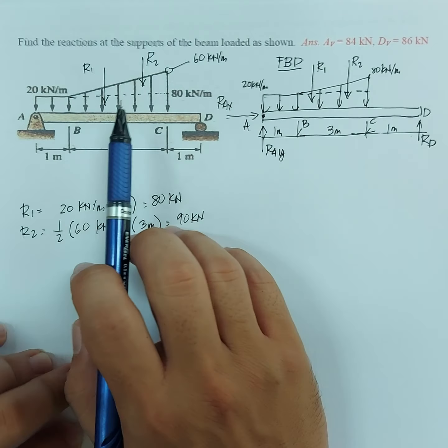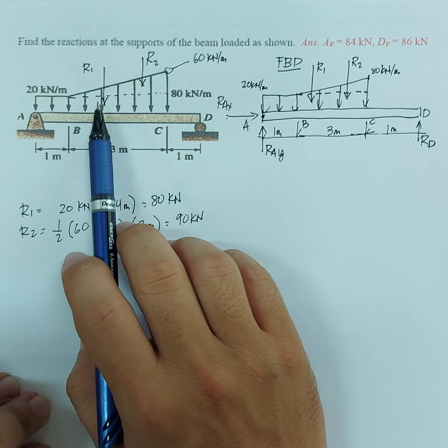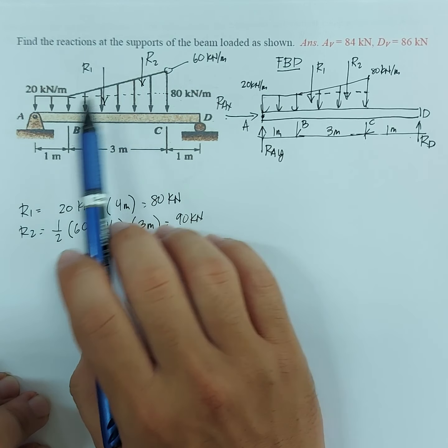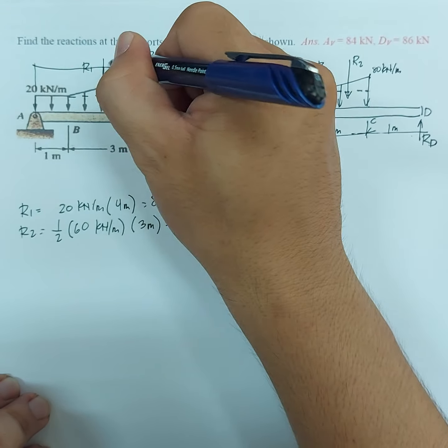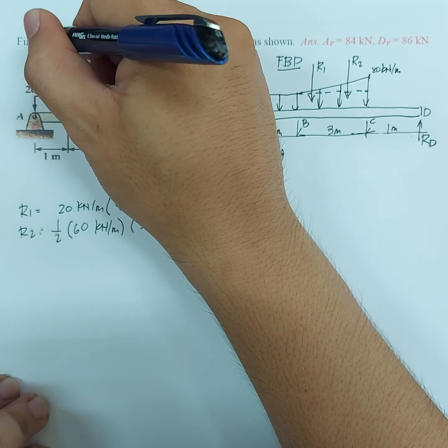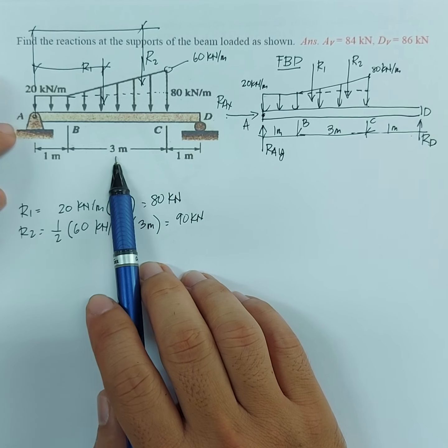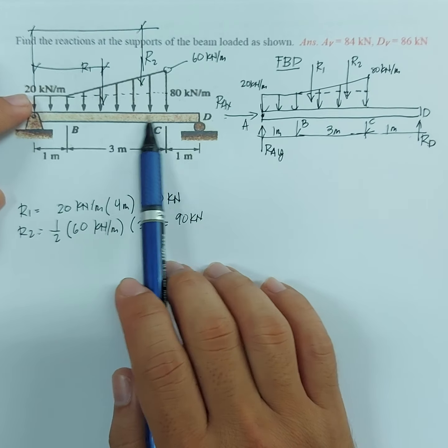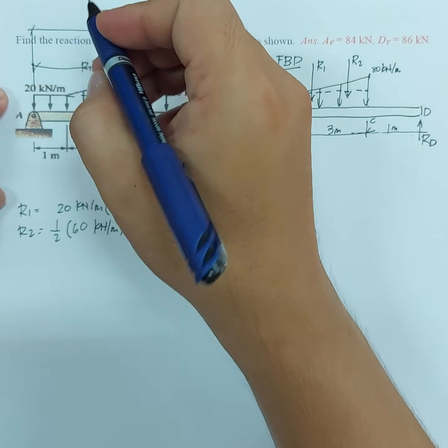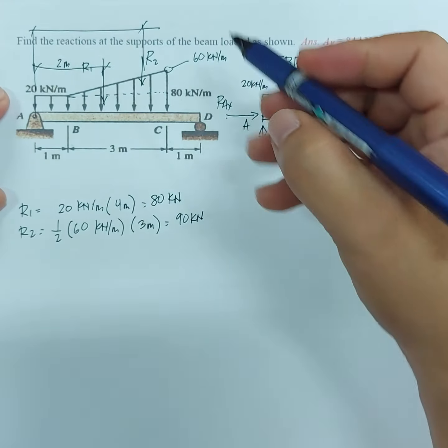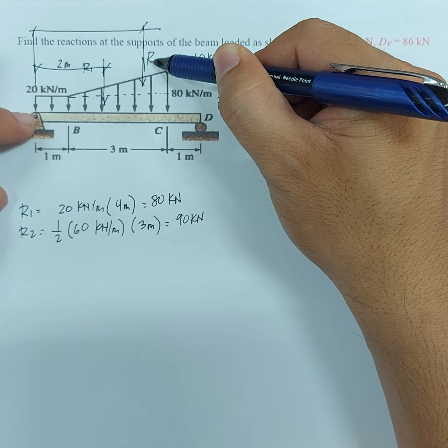need to know yung perpendicular distance, o yung moment arm ng R1 relative to point A and R2 relative to point A. So, anong distance ito? R1 from A, and then we also have R2 from A. So, R1 natin, so 4 plus 3 divided by 2, so that is 2 meters. And this distance, R2 from A, okay.